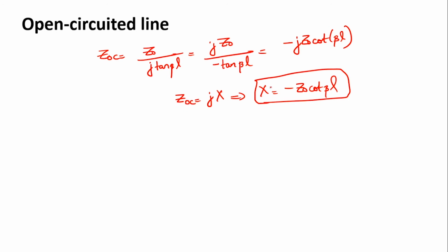Hope you know the difference between X and Z. Z is the impedance value. Z is equal to R plus JX. This is impedance value. Impedance value is equal to resistive value, resistance value, the real part. Okay, this is the resistance part and this is the reactance part. It can be either XL or XC, inductive reactance or capacitive reactance. So here you got like this X.